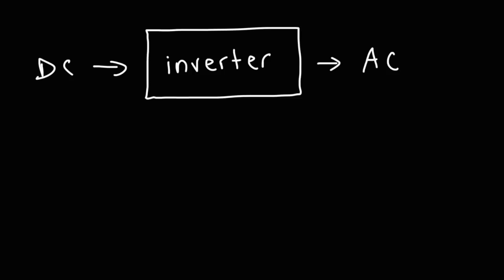So I'll give you an example in my case. One time the power was out and I needed to do some work on my laptop, and after the battery in my laptop ran out, what I had to do was I had a 200-watt inverter. That may not be the exact power, but somewhere close to 200 watts. I connected it to the 12-volt DC outlet in my car, and this inverter converted that energy to 120 volts AC, and I was able to connect my laptop to this inverter to charge up the battery and to get some work done on it.